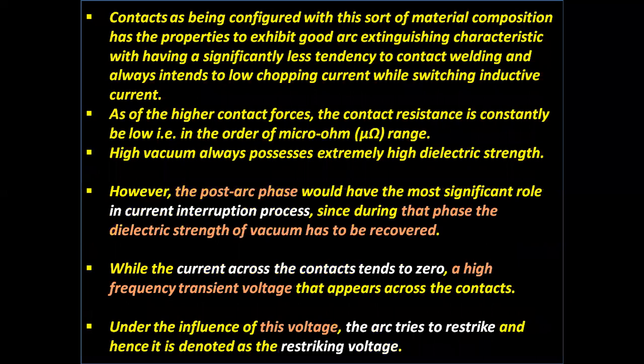Contacts configured with this sort of material composition exhibit good arc extinguishing characteristics, with a significantly lower tendency to contact welding, and always a low chopping current while switching inductive current.